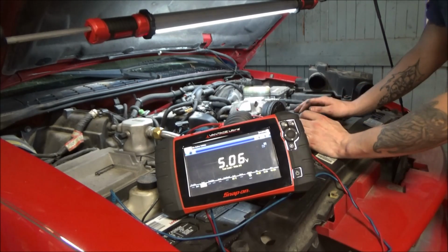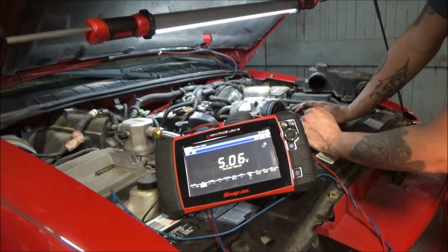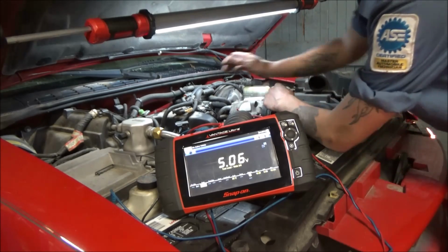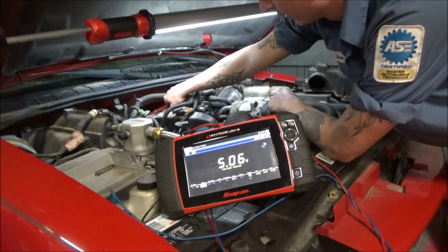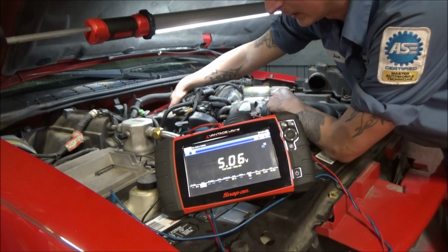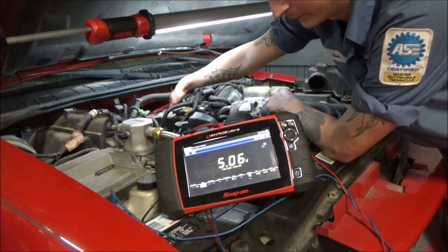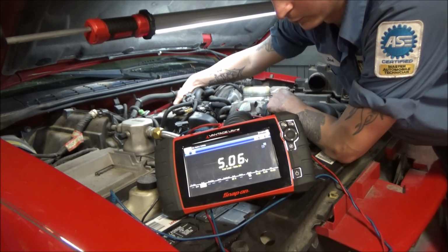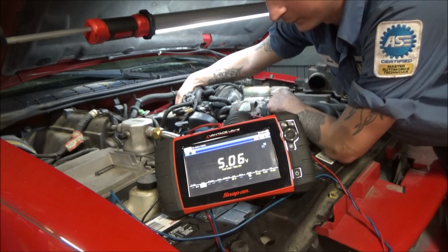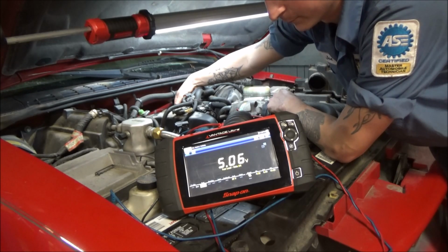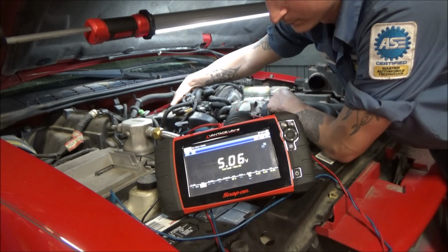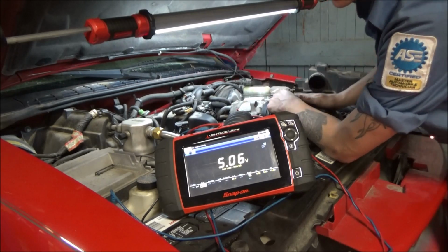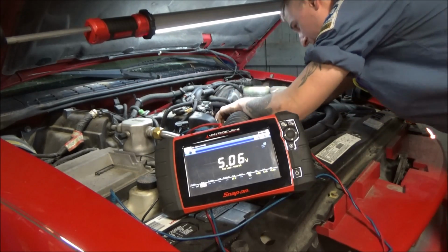So nothing wrong with that reference, but you've got to remember how this thing was failing. We were dropping this signal out at the lower portion of its range. So what I'm going to do is slowly move this throttle position sensor through its range, and I just want to keep an eye on this reference voltage, and you guys should be able to see that pretty good. So I'm slowly opening this throttle here, guys, and we're watching this reference number to make sure it stays consistent, and it does. Moving back to the closed position here, and all the way to closed. And yeah, that looks good. So not suspecting a reference circuit issue here, guys, whatsoever.